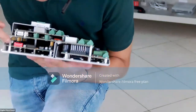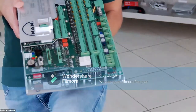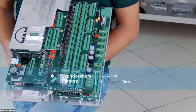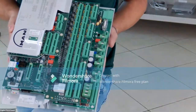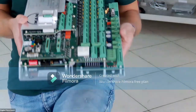So the external ones, 1 and 8, are in the off condition, 2 to 7 in the on condition. 1 and 8 off, 2 to 7 on. You will notice below the DIP switches a label with the color of the DIP switch. The names of these DIP switches are color DIP switches, from the side of the MPC.